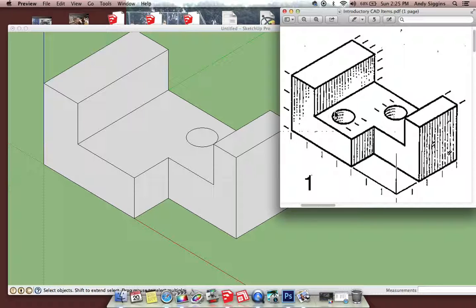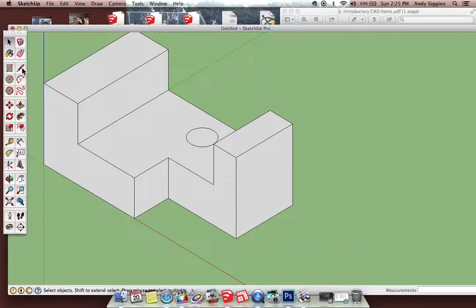We can also see that the distance over here and on this side of the circle are definitely different, so I can't say it's centered. It's the one area I wish there was one extra measurement or indicator as to where the center of that circle fell. But I'm feeling pretty confident that the center of the circle is 1 inch in from this corner and also 1 inch in from the front edge. So we'll go about marking the center of that object.